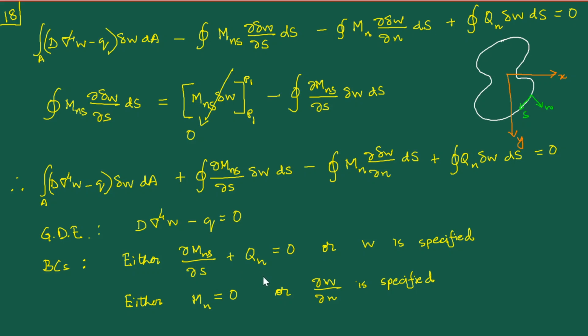That entails another set of transformations, but those are quite familiar to you, if you think in terms of going from the xy coordinate system to the r theta coordinate system. You know how to do those transformations courtesy of what we learned during applied elasticity, but it is also possible to go directly from the ns coordinate system to the r theta coordinate system, but we'll see about that later.